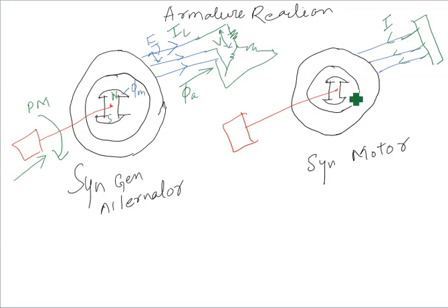First there will be voltage V, and that voltage will create E here, and that E will rotate your magnetic field phi m. That phi m interacts with your rotor, and that makes the rotation. So look at the change. In the generator the energy is coming from one end to the other, but here it is coming from the opposite direction.